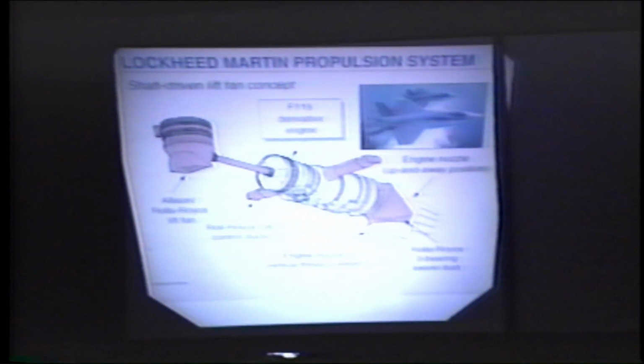Then we have the three-bearing swiveled ducts right here, which lets the force come down vertically. And Rolls-Royce is doing that. They've done a lot of work in the UK on that, and they've got more experience than we have. We designed one back in 1976, and it kind of went away when we went away from doing the VTOLs. But they're doing a good job. That's working well. And of course, then we add a nozzle right here. So that's how we are in the STOVL mode.